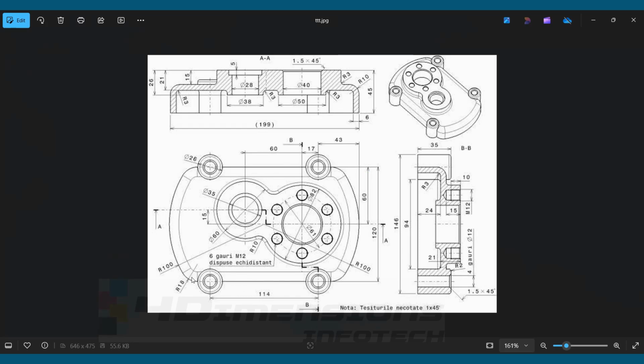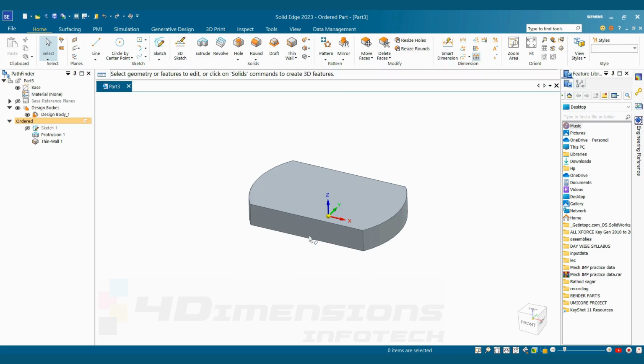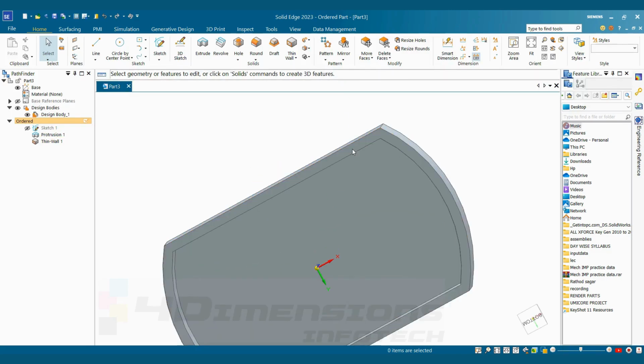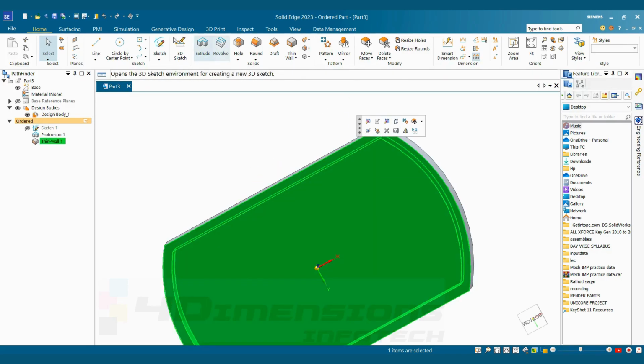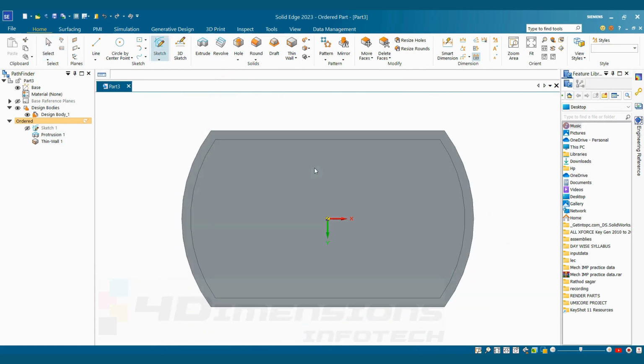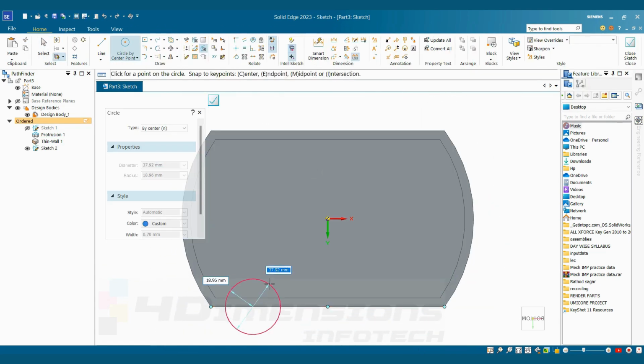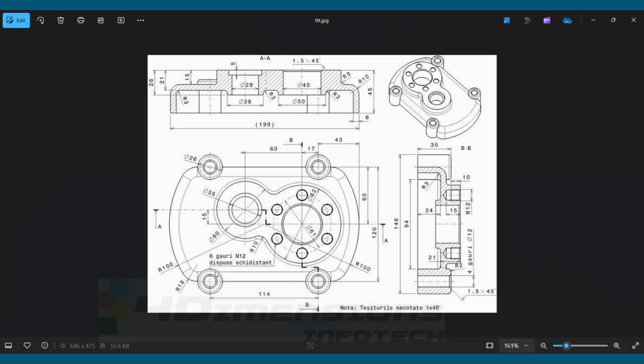Next thing we are going to do here is to make these pillars. To start with these pillars, we can see the bottom face of this pillar is flush with the bottom face of the plate. So I am going to select the bottom face only to make the sketch for this pillar. So I'll select this bottom face here, say sketch on this face. And now we are going to draw a circle here. The diameter for the outer circle is given as 26 and the position is, the total distance between the two cylinders is 114.